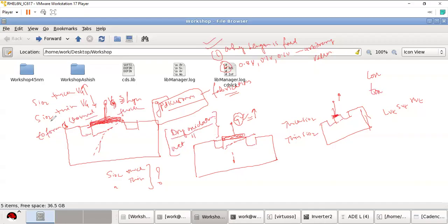So does your threshold voltage. Threshold voltage is the voltage at which the channel is formed. Therefore, your threshold voltage depends on the fabrication process, on whether your SiO2 is thick or thin. So there are many parameters in your MOSFET that depend only on the fabrication process.